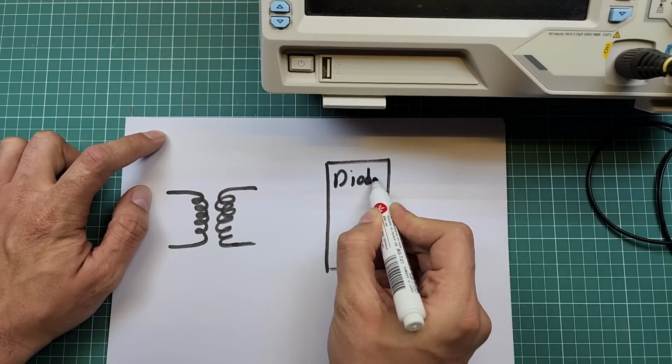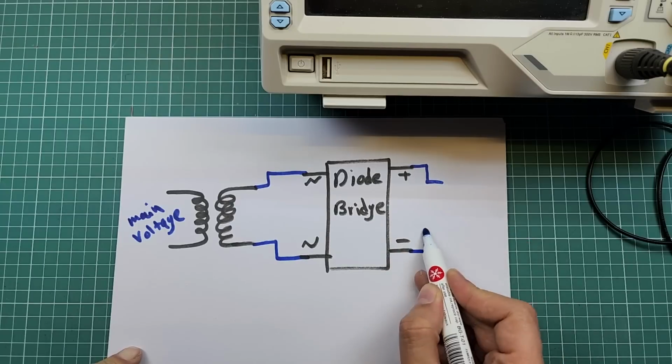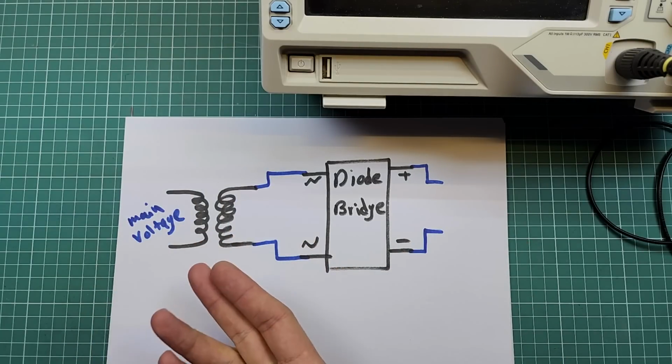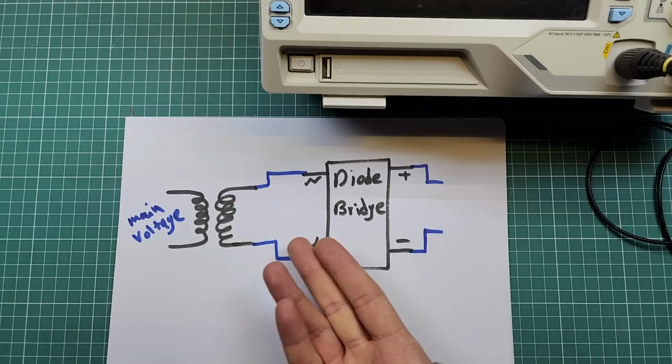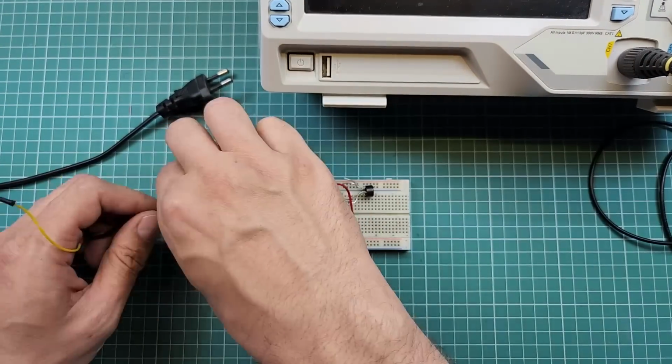So, in applications that need more precision and higher quality, multi-layered ceramic capacitors will be a better choice compared to single-layered ceramic capacitors. Note that it's not only the precision of the capacitance value that makes us choose a specific capacitor type. Sometimes the capacitance itself is the key. For example, in linear power supplies. This is a transformer that is connected to mains power to step down the voltage. I'm gonna set up the circuit and probe the output after the diode bridge.